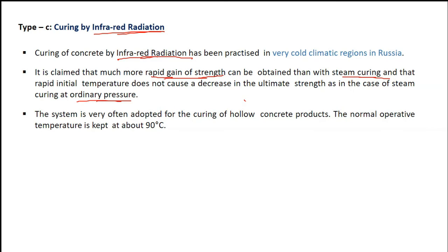So you are going to achieve proper ultimate strength of concrete, and at the same time the hydration of cement is going to be carried out quickly, and the concrete is going to achieve its strength quicker, and the temperature that is maintained usually is 90 degrees centigrade.